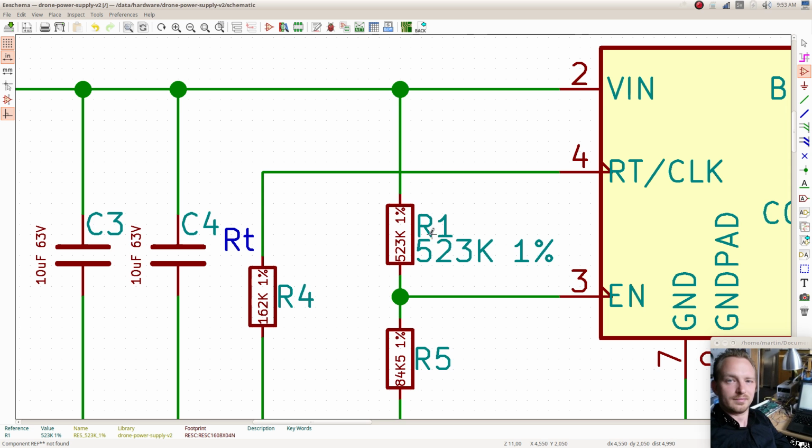The problem is that if you use the same template for every single resistor and you just change this string here, then you cannot have links in your library, which you do once and then reuse in every single schematic. You cannot have those links saved in the library. You have to have them locally in your schematic. So you have to do the specialization of each component locally in the schematic, which I think is both error prone, and a lot of double work for every single component.